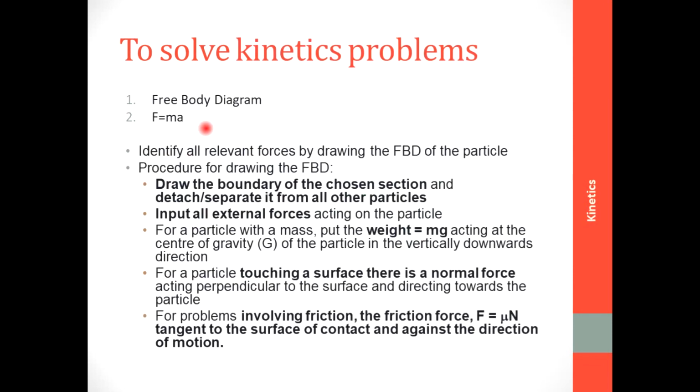Okay, to solve the kinetic problems, we can use a free body diagram and F equals ma. Okay, for the first step, we need to identify all the relevant forces by drawing the free body diagram of the particle, and then draw the boundary of the chosen section and detach or separate it from all other particles.